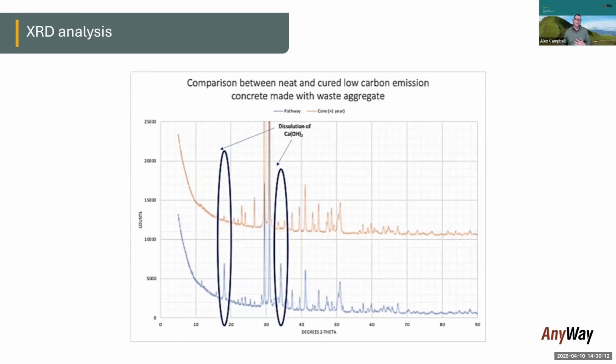When we talk about hydraulic materials, calcium is the backbone of hydraulic reactions. Firstly, because of its association with hydroxide, it increases the pH significantly, and that pH can help to open up reaction sites on aggregates. Certainly in clay materials, calcium fits perfectly into the interlayer spaces. So calcium is one of these magical elements when it comes to hydraulic chemistry.